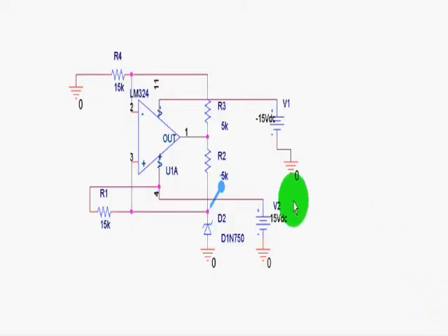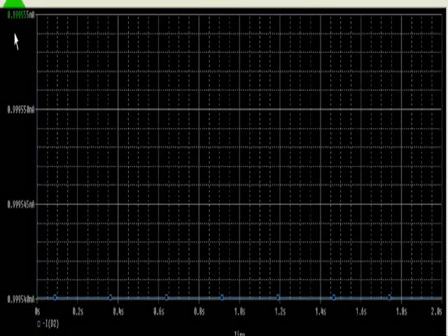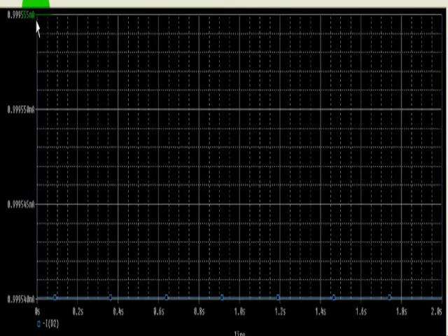In this circuit, we just flip the Zener diode around. Here's the simulation for the Zener diode in reverse. And you can see that there's some initial instability again, but eventually it levels out at about 1 milliamp, which is the ideal value that we were looking for.